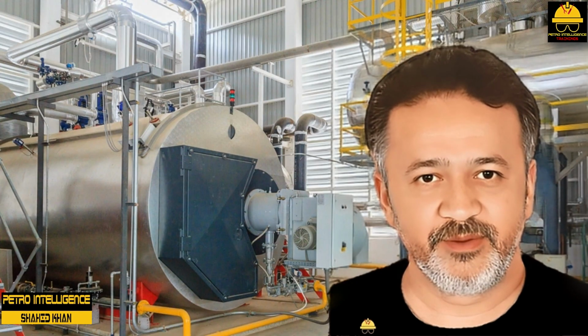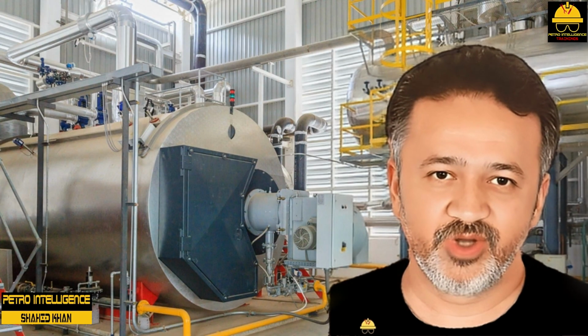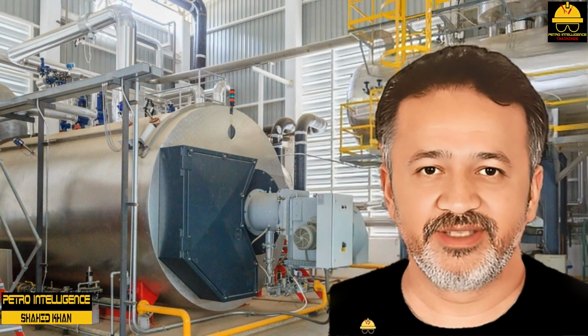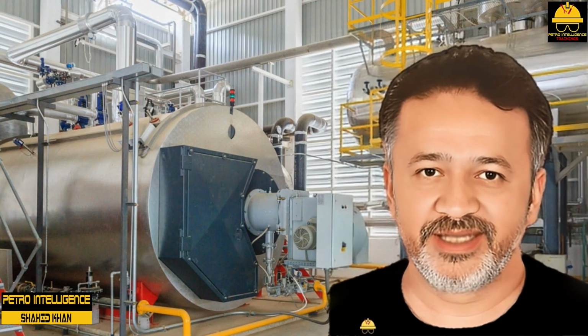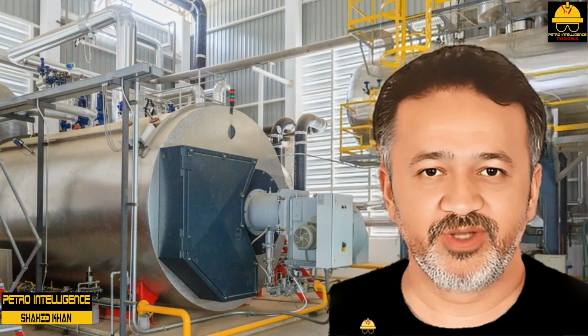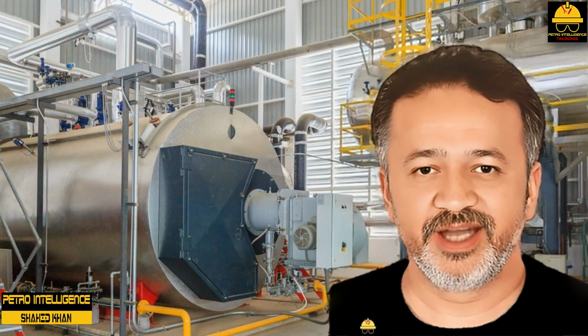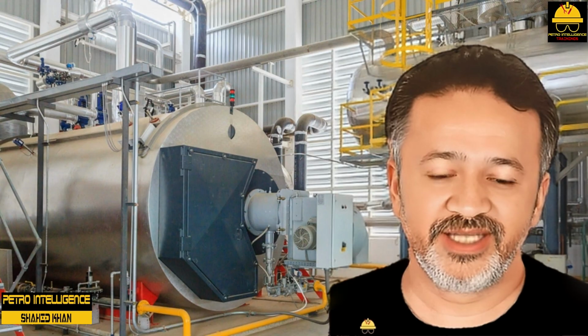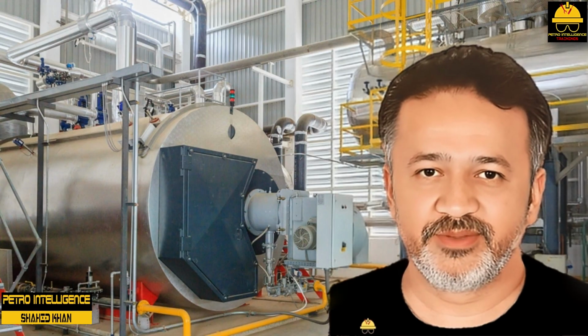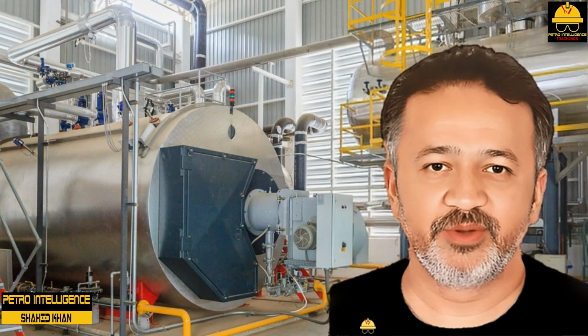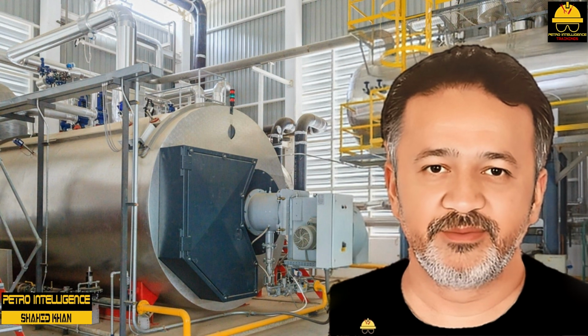The most common type of large commercial boiler is the water tube boiler, which consists of a furnace that contains an upper and lower drum connected by tubes. Circulation through the system depends on density differences in the water in the various tubes. This type of boiler produces superheated and desuperheated steam.